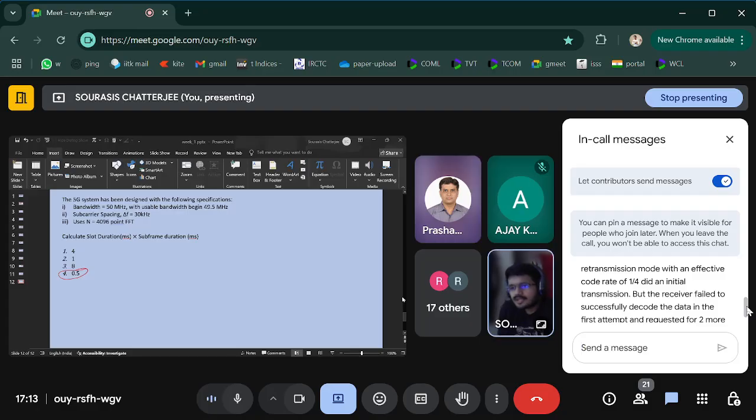Yeah, true. But this term, effective code rate, I find a bit confusing. Compare with the example in the lecture: even if the user asks for 3 by 4, the transmitter actually uses 1 by 4, and in the first transmission it transmits an effective code rate of 3 by 4. For 3 message bits and 9 parity bits, it ignored 8 parity bits and sent only one, and checks whether that is effective. That is puncturing, right? Yes, that is puncturing. So even in the original transmission, puncturing happens.